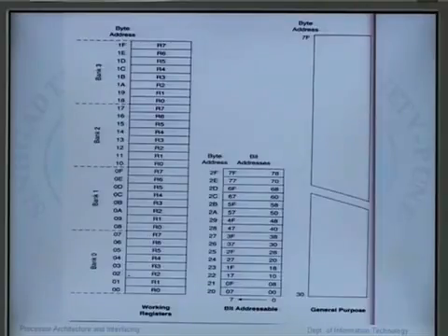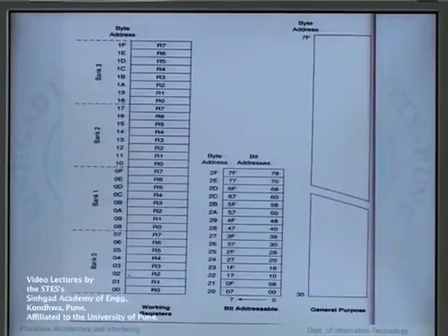Thus, for example, bit address 4FH is also bit 7 of byte address 29H. Addressable bits are useful when a program needs to remember only a binary event such as switch on, light off, etc.